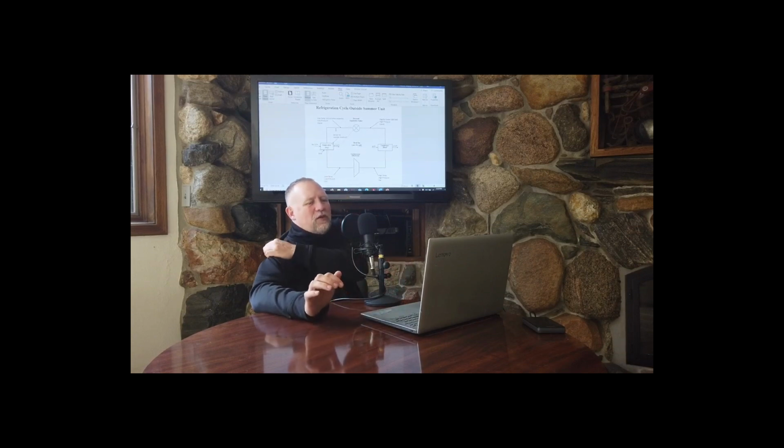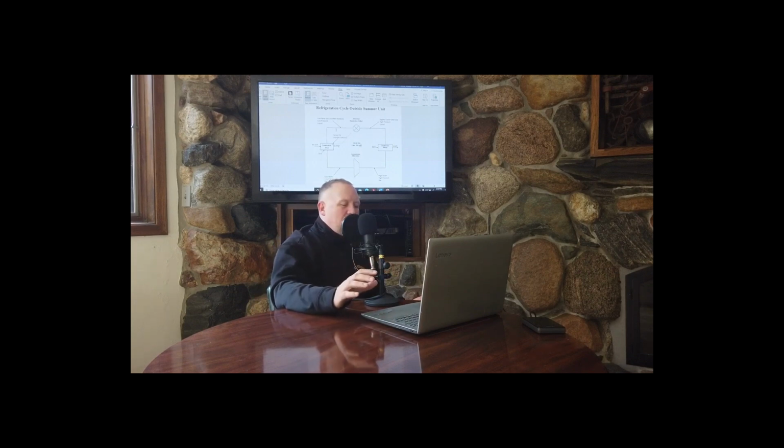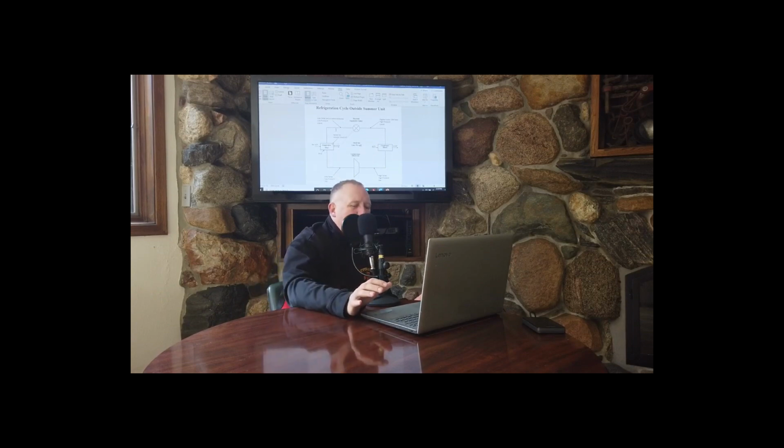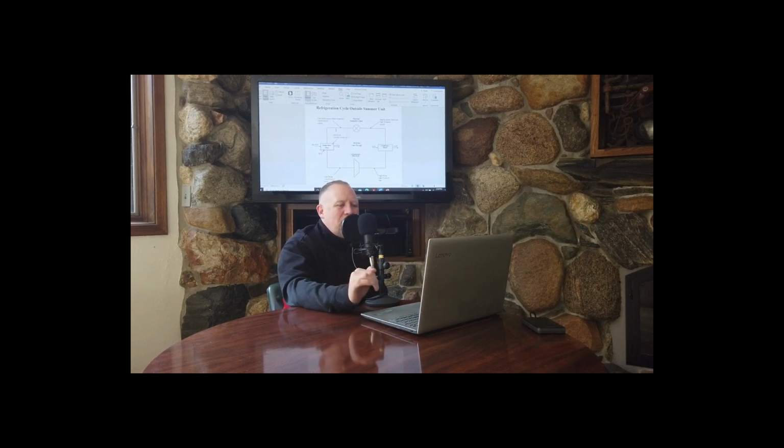Well, that's where we get into variable volume systems, and we looked at this in Con E 251, if you remember. The variable volume systems like at the DMAC project. When we looked at the mechanical sheet metal drawings, there's a box for each space that allows varying amounts of cool air into that space. It controls the temperature that way.